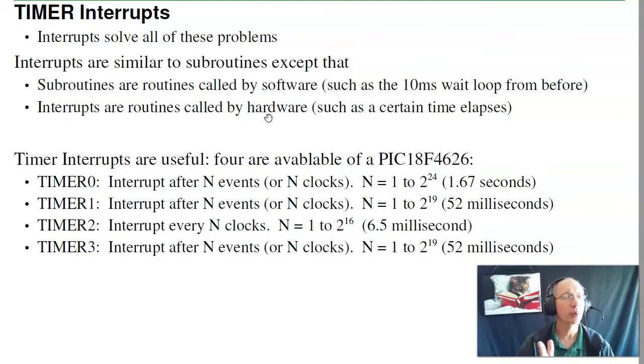One way to think about interrupts is sort of the way classes are handled. One way is polling. I could sit there and stop every 5 minutes and go through the class one by one and ask if there's any questions. Continue on the lecture for 5 minutes, stop the class and do polling again. Really inefficient. A better way is actually the way we run classes. I give the lecture. If somebody has a question, they raise their hand. And then we stop the class, handle the question, then go back to where we left off.